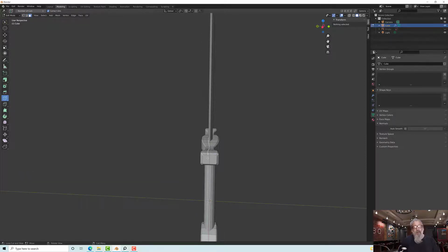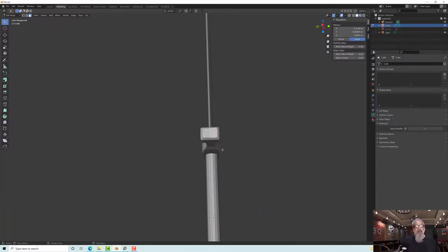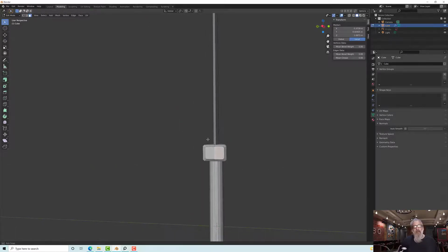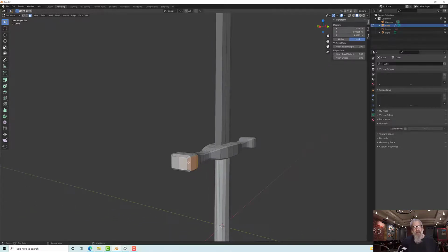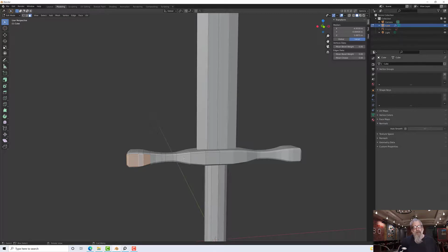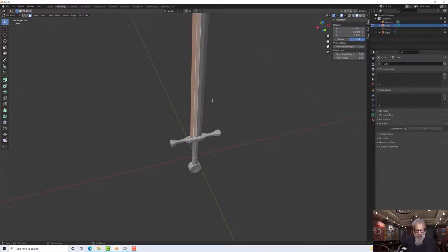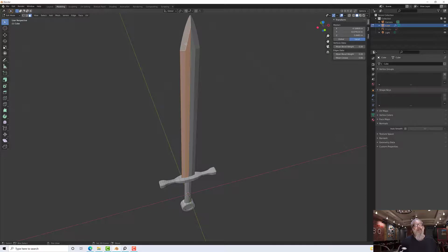Let's get to a side view. I just want to select something first, so let's go to W to select mode, and then I'll use the 2 key. It's this side. Okay. Sorry, my brain is clearly failing me. I want to select all of the bits on the blade. Let's do this bit by bit, shall we? If I press the period key, it will focus for me, so that should do the job.